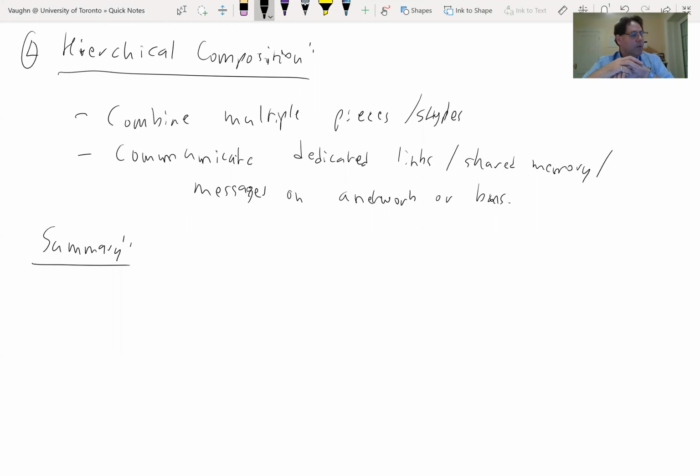You want to be using some of the more customized hardware-centric solutions for the heavy lifting, but you can combine those with easier to program solutions, things that are better at control flow, like soft processors, for simpler control, like finite state machines that are controlling a bunch of hardware units.